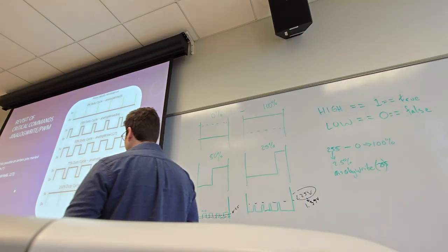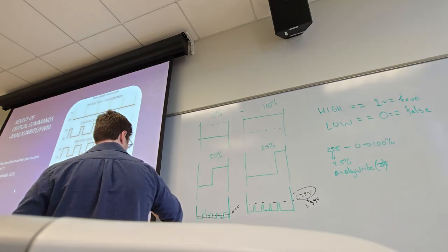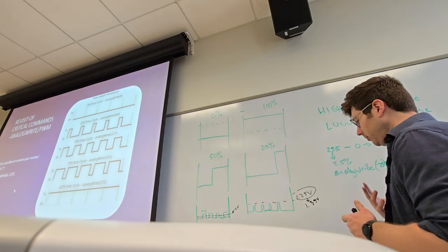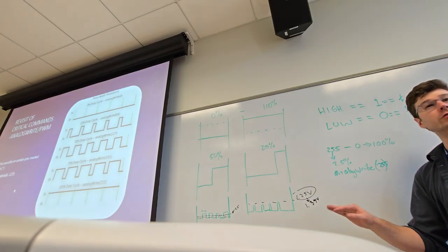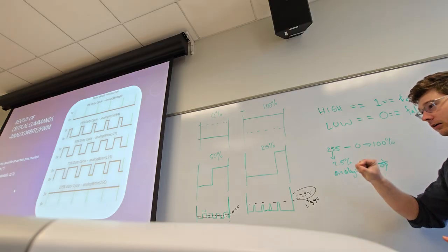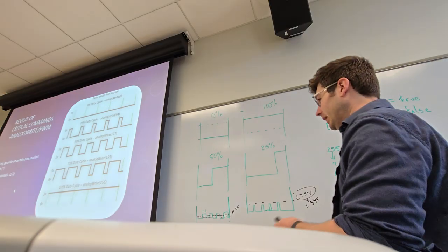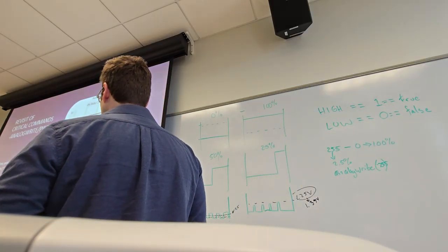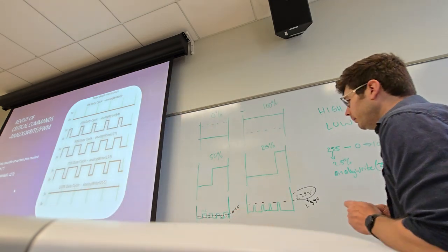So most Arduinos, again, the granularity with which we can control this signal is a selling point of the processor. Different ones have 8 bits, some have 10 bits or 12 bits, right? The finer you can tune that signal, the closer you approximate highly accurate controllers. We can also control outputs with this.